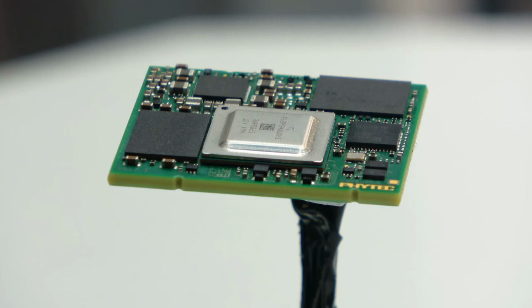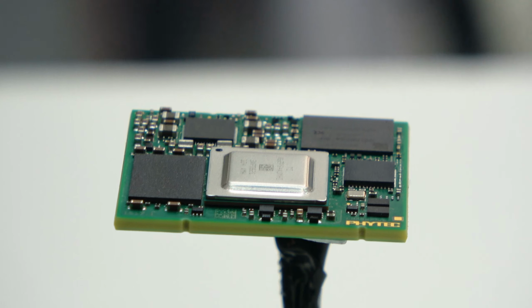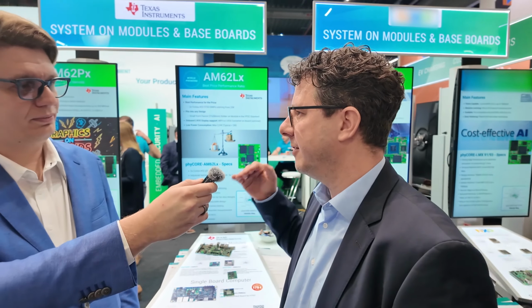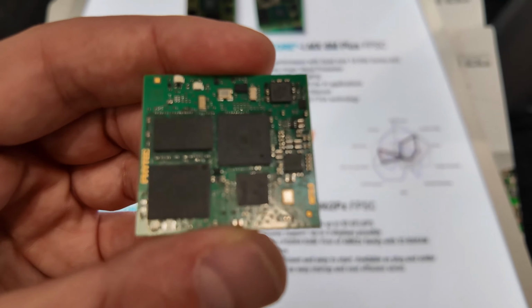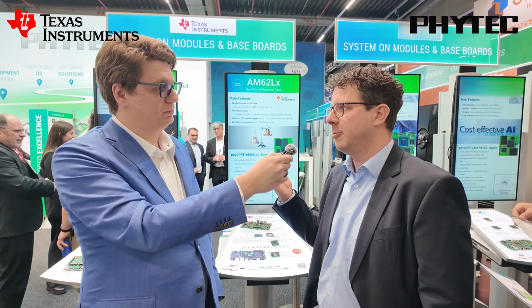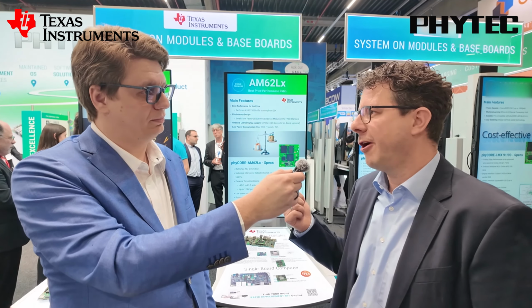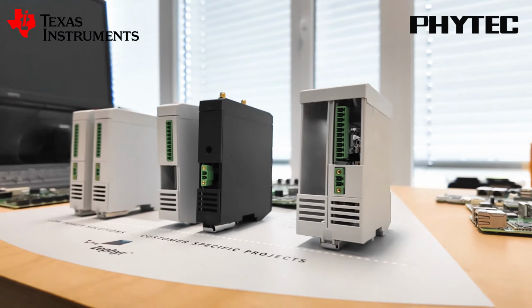So Yves, tell me, what have you done to really optimize your SOM for the AM62L platform? Well, we followed the idea of a high-performance, low-cost product. So we made sure that we optimize the BOM costs for this product. PCB costs are very low because we were able to save in layers. We have made it scalable with other products from TI, for example, the AM62P. So they're pin compatible with easy interchangeability. So if you need an upscale in terms of graphics performance, you can just switch, or you can create one product that has low graphics and then just create another derivative out of the same product with more performance.